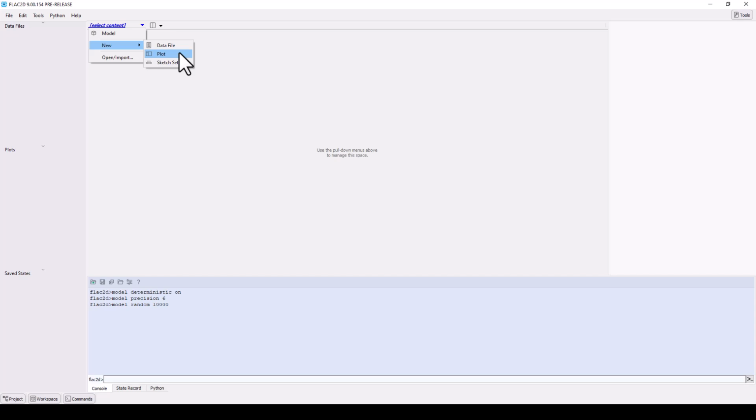Sketch sets are used to create and mesh the model using drawing tools or imported CAD files. Interactively modify model properties and constitutive models, define groups, work with structural elements, and more via the model pane. This workspace may be split into a series of tiles, with flexible content.